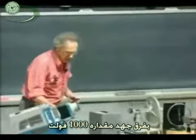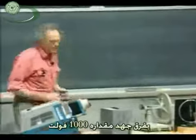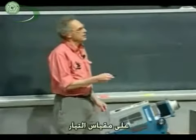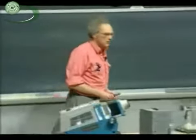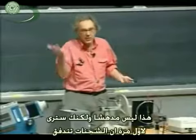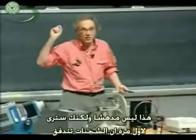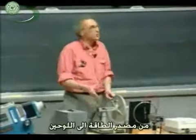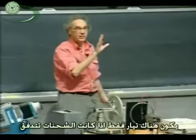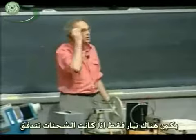There's a potential difference of 1000 volts. And as I do that, you will see a very short surge here on this ammeter. That's not very spectacular, but at least you can see for the first time in your life that charge is actually flowing from my power supply onto the plates. And you will see, psh, and that's it. It will only be a current as long as the charge is flowing.